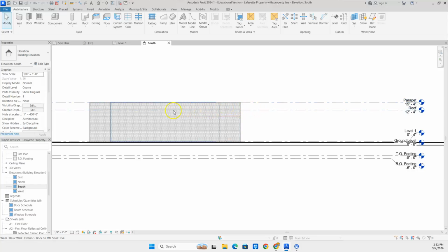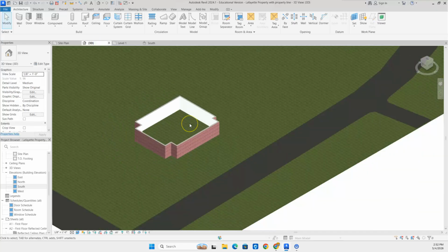And again, because the roof itself is going to be sitting on the roof level, we'll have a 3-foot sort of wall here between the roof and the upper edge here. So when maintenance people go on here, they don't just walk off the roof. We don't want that. We can also hide your air handling units and things like that on that area. So that is really all you need to do for this video.